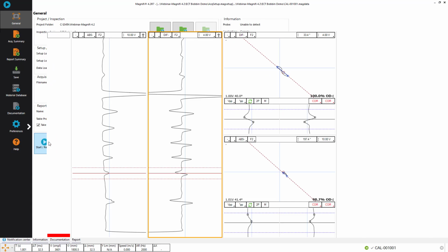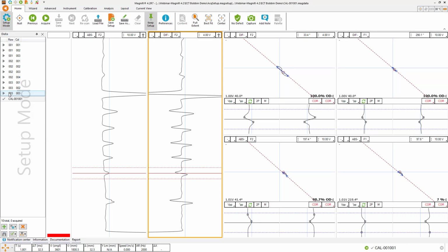So when I go back, I have already a list of tubes created. I could also click on a specific name here and click the plus button to create a new tube. Now it has the row number 4 and column number 3. I can edit the number back to 1, and then from here I can change which row or column I'm incrementing, and now I can add more columns to it. So it could be done manually or more automatically.